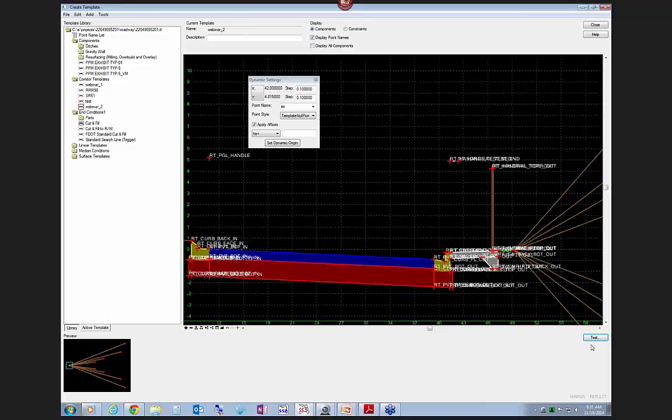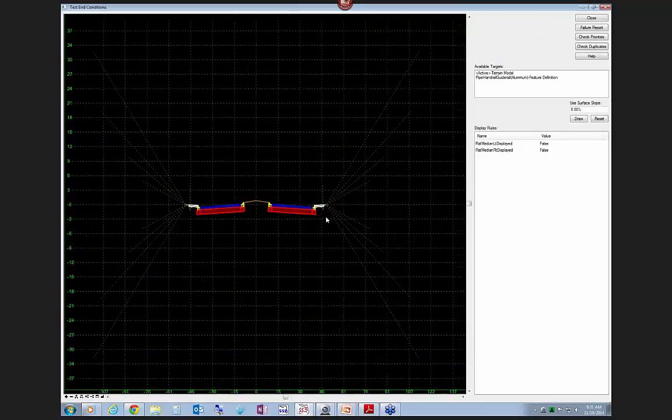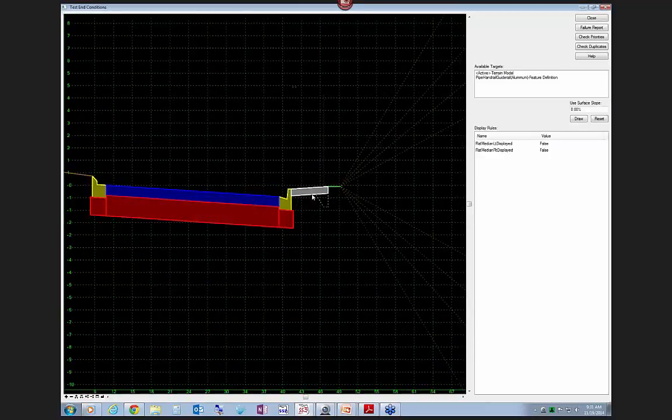So if you do a test now, you'll see that in my normal situation here, I have a normal sidewalk because I don't have a target. I have it drawn in the target for the pipe rail. But if I draw that in here, notice that as soon as I get left of that begin point, it's going to trigger on the pipe rail and also the sidewalk footer that goes with a pipe rail, and it draws it in there.